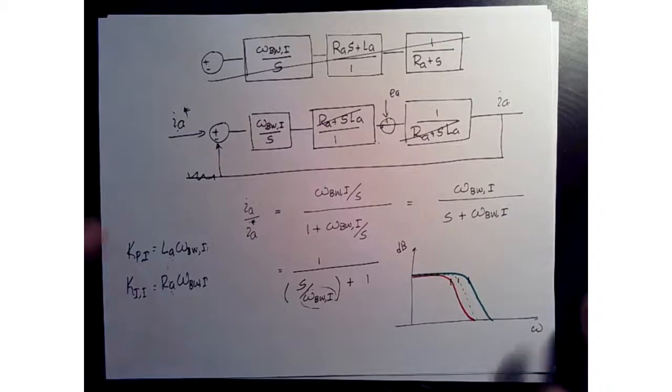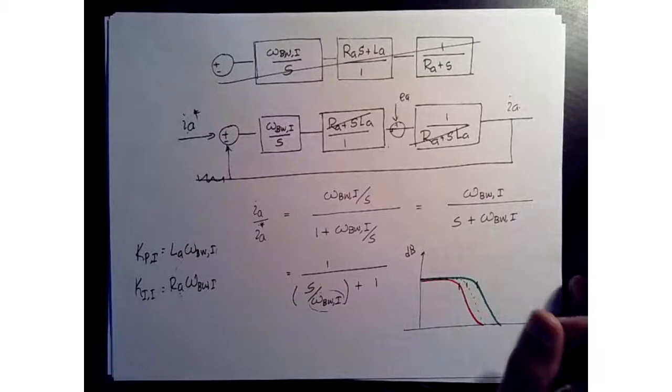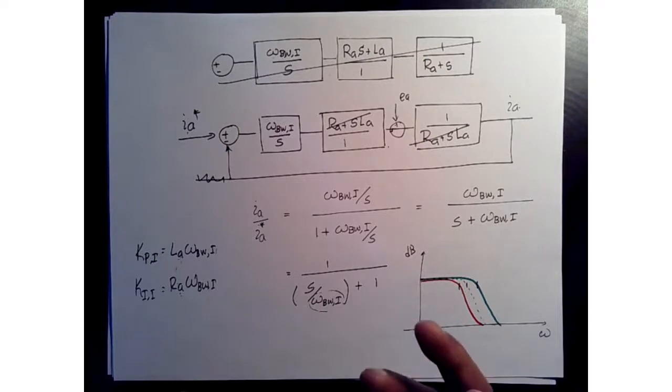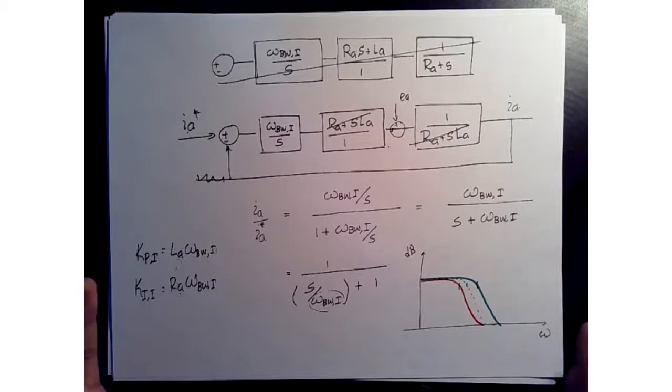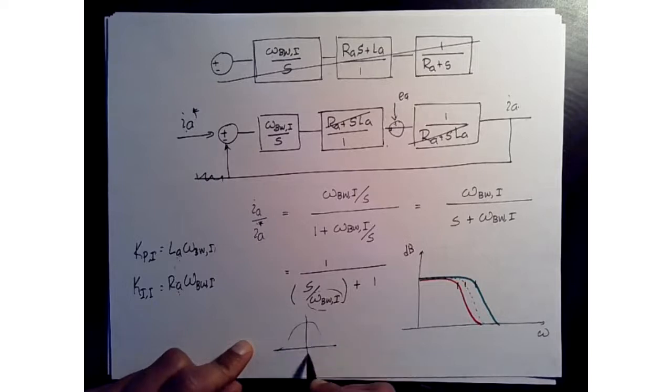Well, with a datasheet, if you buy a motor with a datasheet, most likely they will have a nominal value, because motor production is mass production. They're made in large numbers, and in general they cannot say this motor has this resistance, this inductance. So what they do is they take a whole batch, find the distribution, and then give you a mean value.